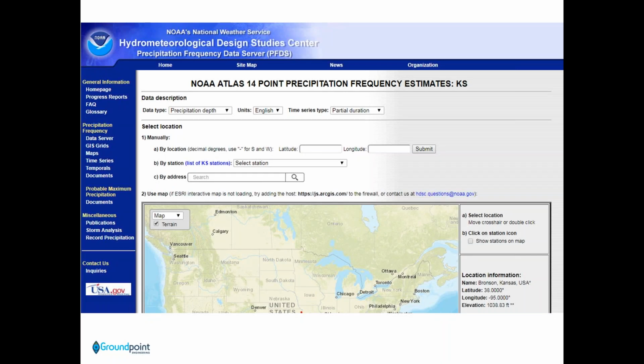And talking about standards for culverts, we also have a standard for precipitation. Remember, we're not talking about just one storm, but a range of storms, the 1 year, the 2 year, the 5 year, etc. So the Python code is hardwired to read the standard NOAA Atlas 14 precipitation estimates, which you can go and download in a standard format. It'll also read other formats. For example, the Northeast Regional Climate Center publishes similar estimates, which actually include climate change factors, but the tables are transposed. The point is that we want to standardize the precipitation data so that the peak flow calculator can just go and look up a table and know where to find the various values.